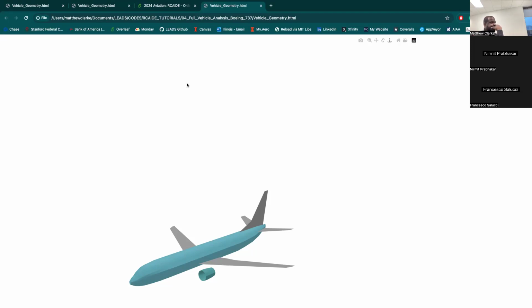Have you validated this VLM model? Is it able to do the structural or fluid structure interactions and the fluid interactions both? The VLM model is just a model for the actual aircraft itself, or any lifting surface. It has been validated, and we have a paper on it. The reason we wrote a VLM model is because we wanted a model that can do subsonic, transonic, as well as supersonic regimes.